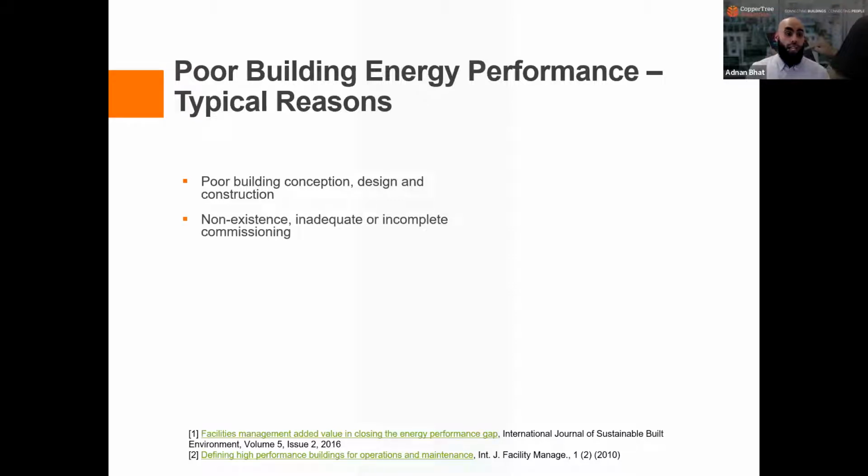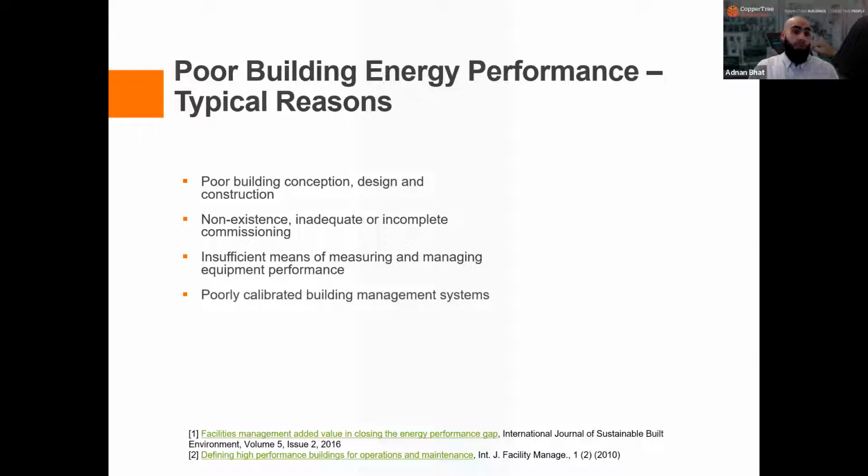Non-existent, inadequate, or incomplete commissioning. Insufficient means of measuring and managing equipment performance. Now, good data is critical in implementing the right strategies and processes, and extracting that data, giving it a meaningful structure, and deriving intelligent insights is a challenge for many organizations. Poorly calibrated building management systems, lack of metering. Good meter and sensor data is important to collect valuable system and energy-related information for us to be able to make better, more informed decisions about our facilities.